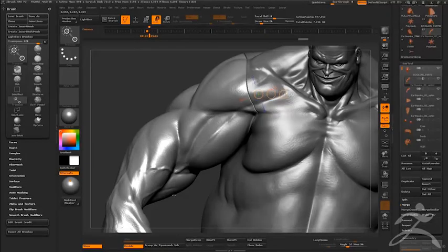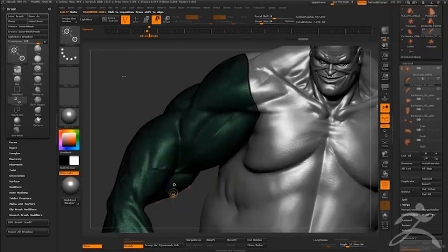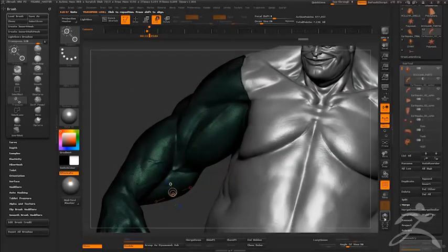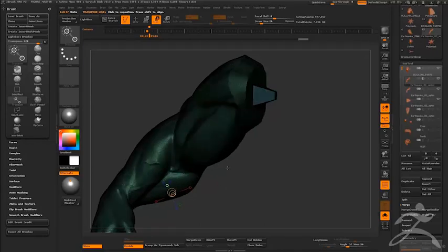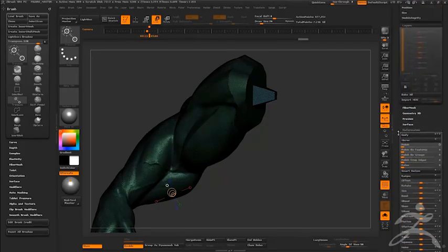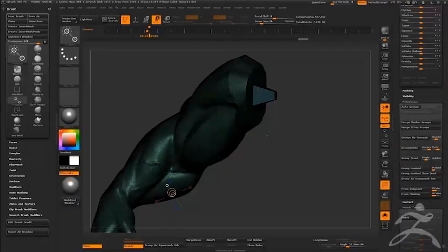So you've seen I've been doing a lot with changing the colors of these objects, right? Well, in this case, the way you tell the Dynamesh engine that I want to remove this from the other thing is you have to give it a special color. And this is the only time you'll see a white color being put on an object here. It's a group that is a Dynamesh sub, all right?